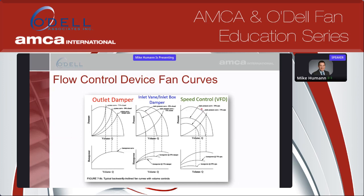And the last one is speed control, your VFD. As I mentioned, we change the fan curve, and as you speed up or slow down the fan, it mimics the normal fan static pressure curve at 100%. If you want to increase speed to 110%, it'll move back out here. And same thing if you go to 80 or 90%, it starts coming inside. You see here we see these big horsepower savings when we're slowing down the fan. But as I mentioned, you do lose some of that static pressure capability of the fan at slower speeds.